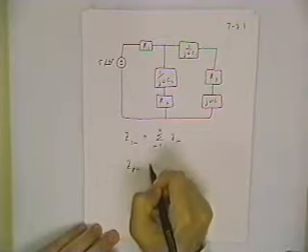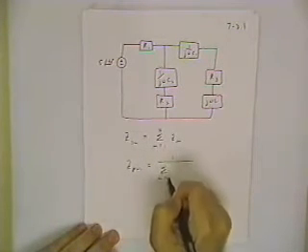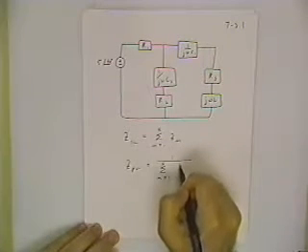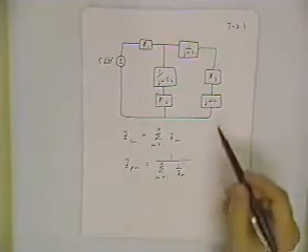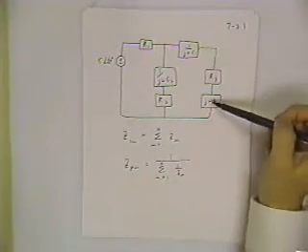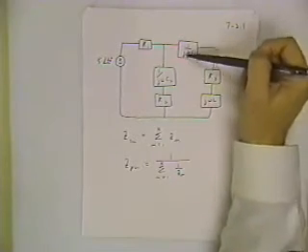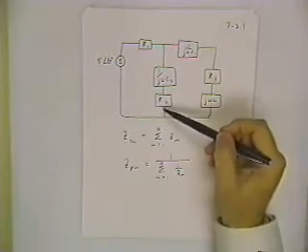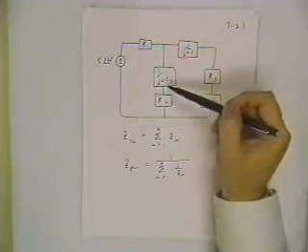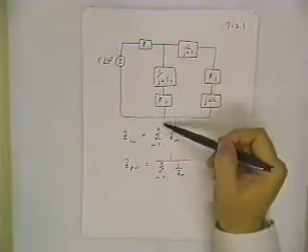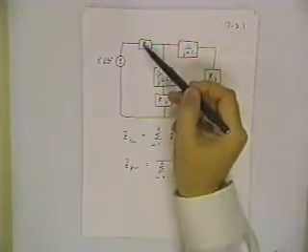For parallel connected impedances, you take the inverse of the sum of the inverses. So with numerical values substituted, you would take one grand total impedance for this branch, a grand total impedance for this branch, combine those two in parallel to come up with a single impedance for this whole network, and then add R1 to that.